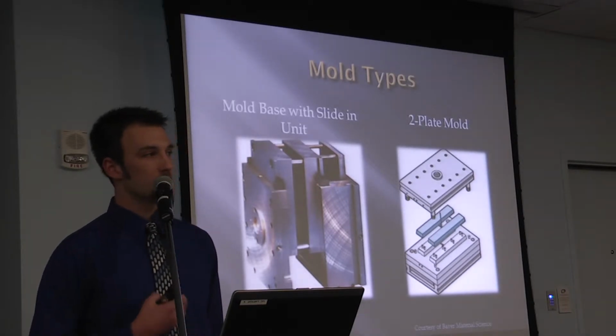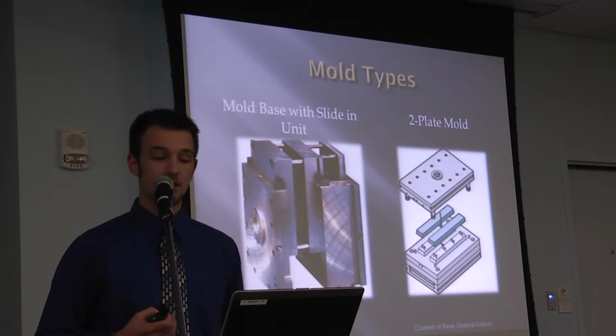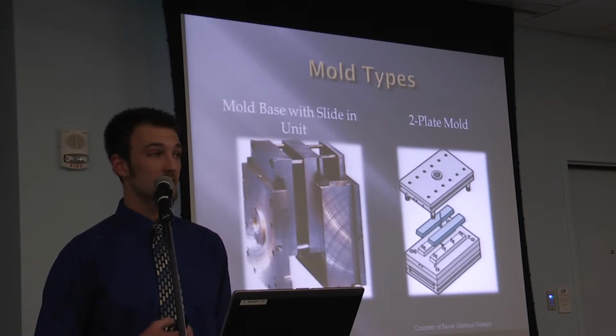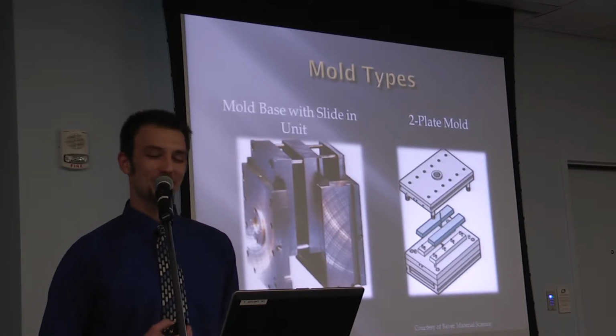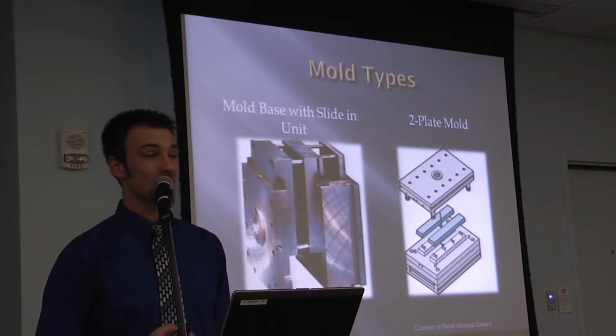The mold types. Here at USI, we have two different types. We have the mold base with the slide-in unit. This can be used in lean manufacturing and teaching applications within the classes offered here at USI, as well as SMED. SMED stands for single minute exchange of die. It does not actually mean a single minute, but rather a single digit, so under 10 minutes is the goal.